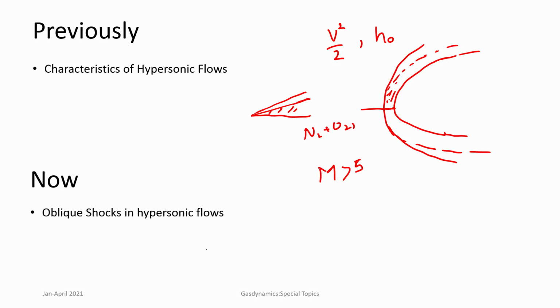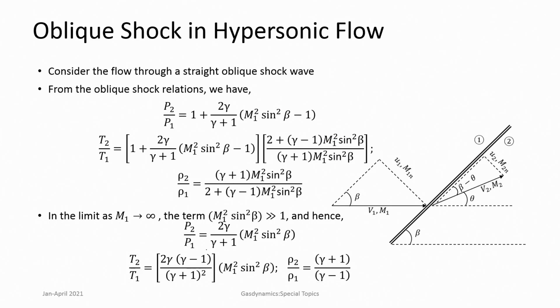Now, in this class, we have seen how complex the physical features in hypersonic flow are, but at the same time certain aspects like thin shock layers, shocks coming very close to the body, and also high Mach numbers, produce certain simplifications. These allow us to extract estimates of the forces around bodies in hypersonic flow using relatively simpler theories rather than very complex theories.